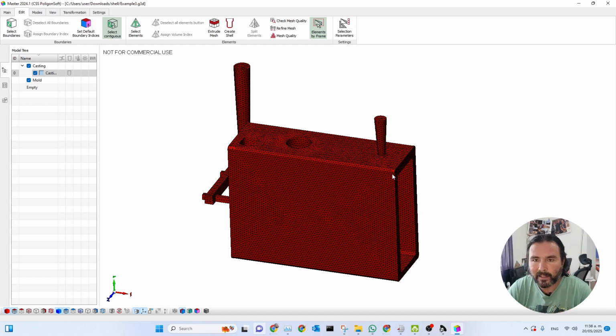Normally, the heating depth of the sand isn't very large. That is, the sand heats up 120 millimeters into its interior, so to avoid the errors implied by using the virtual mold, we can create something like a sand shell around our part. And then, outside of that shell, use the virtual mold to tell it that outside the shell we have the same sand, and this will give us much more precision in our calculation. Let's see how it's done.